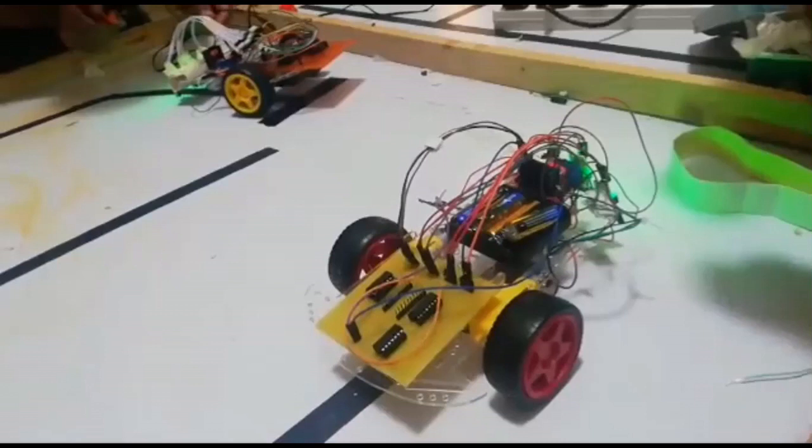Summarizing this project, first we designed the truth table using rudimentary logic. We simplified the truth table, and using those simplified equations, we drew its schematic. Using that schematic, we patched the circuit on the breadboard, and when we had attained the possible combinations, we designed its PCB of suitable size to fit on the chassis kit. After designing that PCB, we performed etching. After etching, we soldered all these components, and after that, we patched all these components on the chassis kit, and our line following robot is ready.